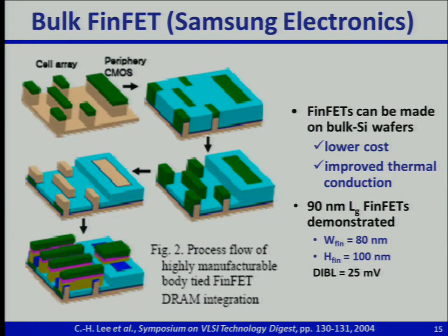So it's not trivial to have planar CMOS devices manufactured side by side with FinFETs. And actually, that's the reason why the foundries or Intel, if you look at their 3D transistor chip, every transistor on their chip is a 3D transistor. It's not like you can select some to be 3D and the others to be planar. All of them have to be 3D because the fabrication process is too complicated otherwise.